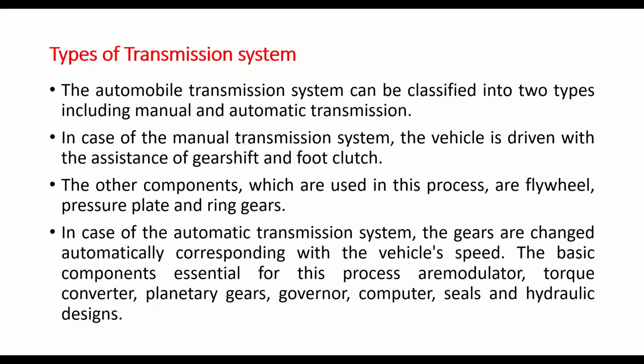If it comes to 19, again it will move to second. So in a city drive, if you are going between 19 and 21 kilometers per hour for 1 kilometer, it shifts the gear multiple times automatically. But that is not the case in manual transmission. You will judge, and when there is a real requirement, you will shift the gear. Otherwise, with plus or minus 5 kilometers per hour, you will be managing with the gears.